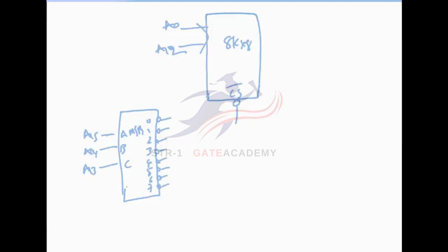And any decoder internally enable is there. Enable is 1 here because this is active high pin. If it is active low pin, enable pin should be 0. So depends on the type of the line, then this should be 0 or 1. And we want decoder should be in active position. So here I connected with the active high pin. This should be 1. And from this, let us assume this third line is connected to the chip select.